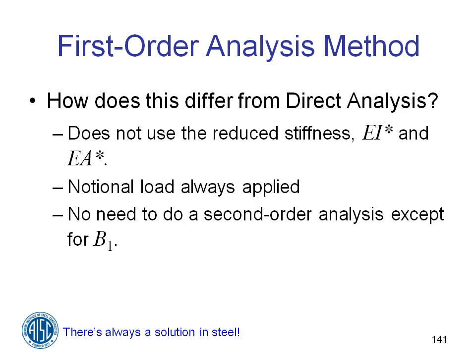So how does this differ from the direct analysis method? All right? It does not use any reduced stiffnesses. There are notional loads all the time in every load combination, gravity as well as lateral. And there is no need to do any second order analysis except for the B1 calculation.